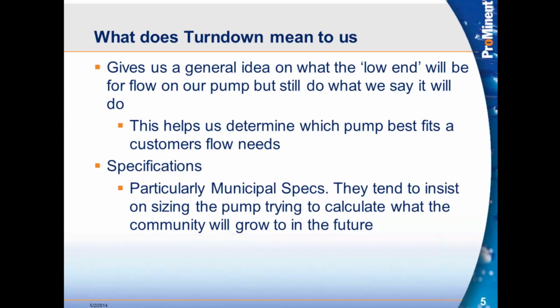Specifications, particularly on the municipal side, they tend to insist on sizing a pump based off of growth in a community. So they'll build a water plant and they want to put a metering pump in to dose whatever chemicals they're putting into the water to treat it. And they'll base it off of growth in that community.